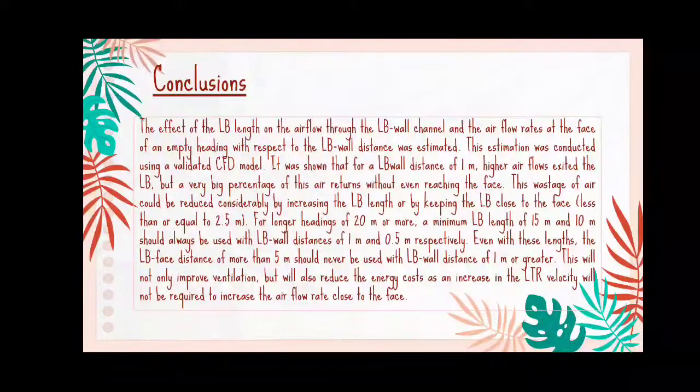It was shown that for an LB wall distance of 1 meter, higher airflows exited the LB, but a very big percentage of this air returned without even reaching the face. This wastage of air could be reduced considerably by increasing the LB length or by keeping the LB close to the face, less than or equal to